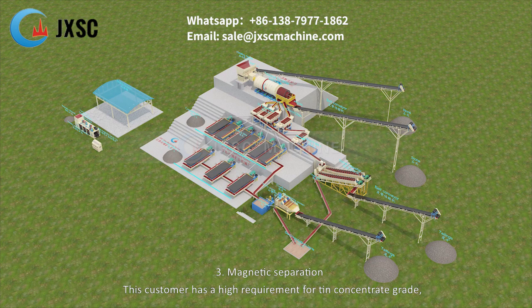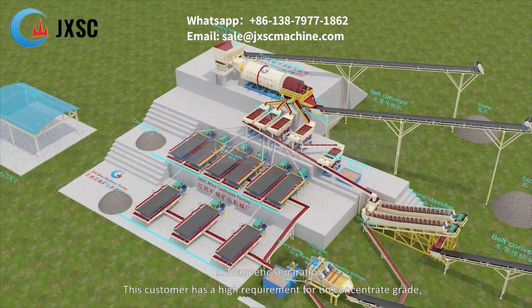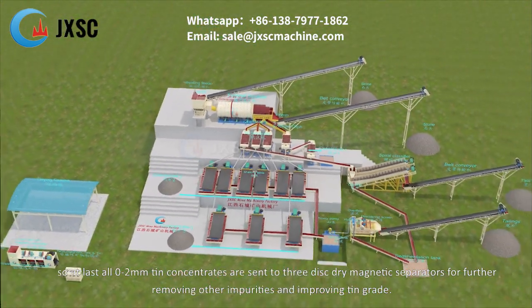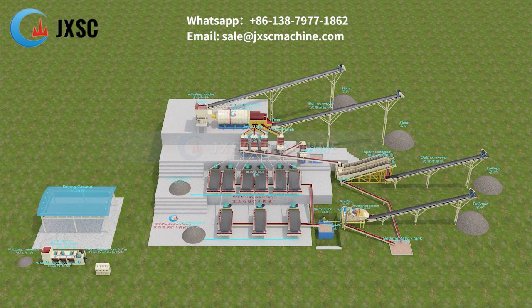3. Magnetic separation. This customer has a high requirement for tin concentrate grade, so at last all 0 to 2 mm tin concentrates are sent to 3-disc dry magnetic separators for further removing other impurities and improving tin grade.